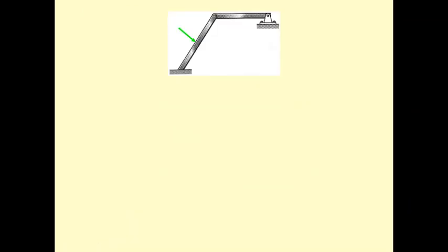This picture is a frame, and this frame has the fixed support here for the column, and then it has the pin support here. This problem is special. The column and the beam have the hinge connection here. The hinge, as we know in statics, when you draw the hinge is going to have 2 unknown forces there.